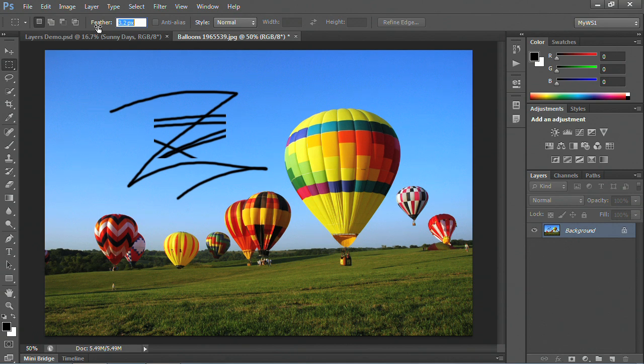Incidentally, if you hold down the shift key when you're using scrubby, it's going to actually move at a higher rate. So here's without the shift. Now I'm going to use the shift, and it just jumps. If you use the alt key, let me make sure I'm using my scrub right. I'm using my scrubbing and I add the alt while I do that. It actually is going to slow it down a little bit, making it move at smaller increments. So that's a little tip and trick with the alt and the shift key.